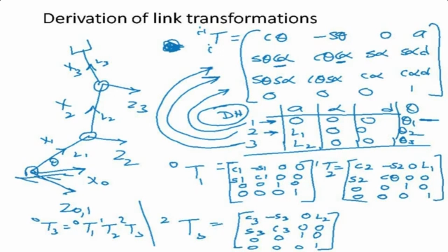So we're going to write a computer program which is actually going to make the DH parameter table, or you're going to enter the DH parameter table, and the computer program will take this array. The DH table is a matrix, and every time it takes one array, or one row, from that matrix, puts it in the generalized matrix and gets the transformation matrix between the two corresponding frames. Okay, and this is generalized, so it can take any frame to any other frame.